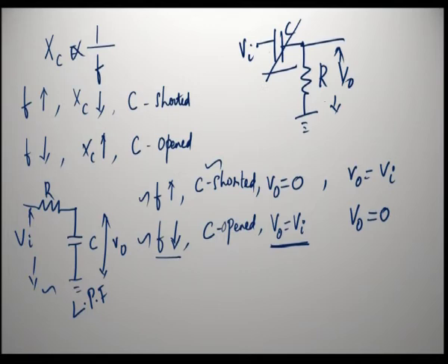This combination of the resistance and capacitance will produce the voltage, whatever the input voltage is given, at the output for high frequencies. So, this is said to be a high pass filter. For the lower frequency, the output will be 0. So, this is the setup of the low pass filter and the high pass filter, and now we can derive the transfer function of the filter.